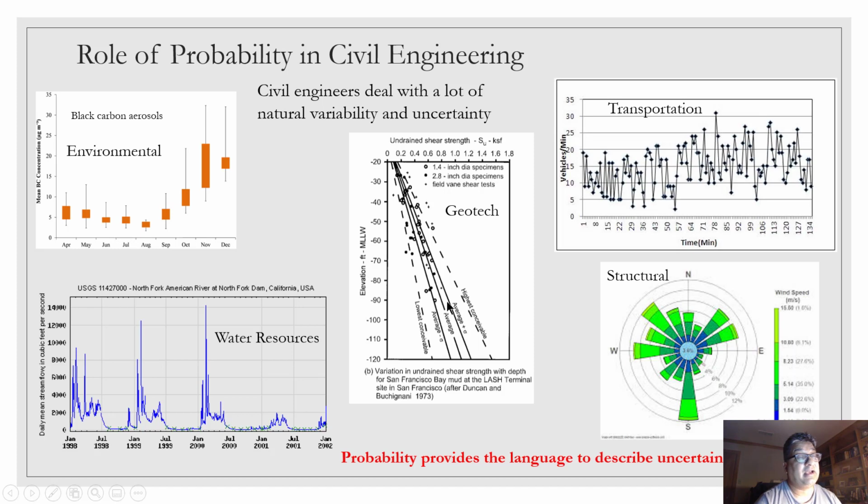So there is an average value, and average plus or minus standard deviation, and you will see that many data points fall in that range, but there is also variability at a given depth. If I take a depth of 50 feet, you will see that the values can be anywhere between 0.1 to about 0.6 kips per square foot. So there is quite a bit of uncertainty and variability as we go to different depths, as well as at a given depth.